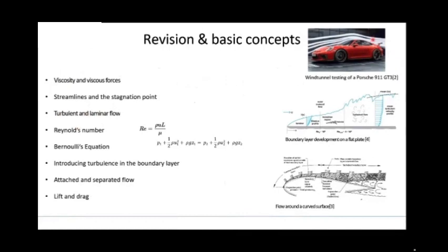At the back of the vehicle here, we can see flow moving in a disorganised way, represented or seen by these smoke particles which are merging. So clearly there is flow travelling vertically in a disorganised way at the back of the vehicle. So organised laminar flow, disorganised turbulent flow at the back of the vehicle.